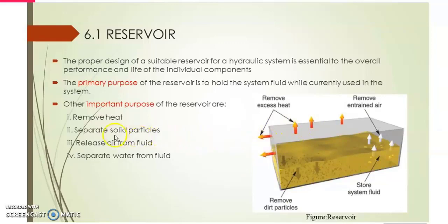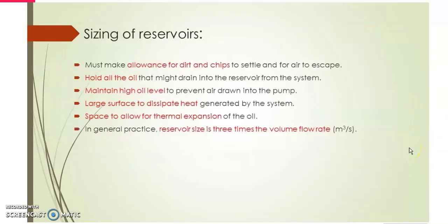The other purpose of the reservoir is to separate solid particles, so we can remove dirt particles, release air from the fluid, remove the entrained air, and also separate the water from the fluid. These are the purposes of the reservoir.